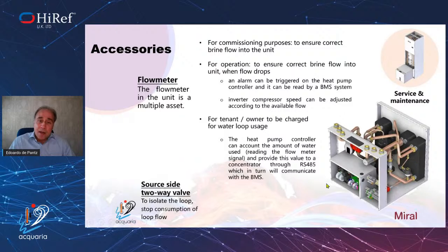And the second point: this flow meter is also very interesting, because the measure of the water flow on the loop side, together with the delta T temperature on the loop side, can give important information to the building manager to charge the tenant or the owner of the apartment for the consumption of the loop energy. And this is quite an interesting possibility.